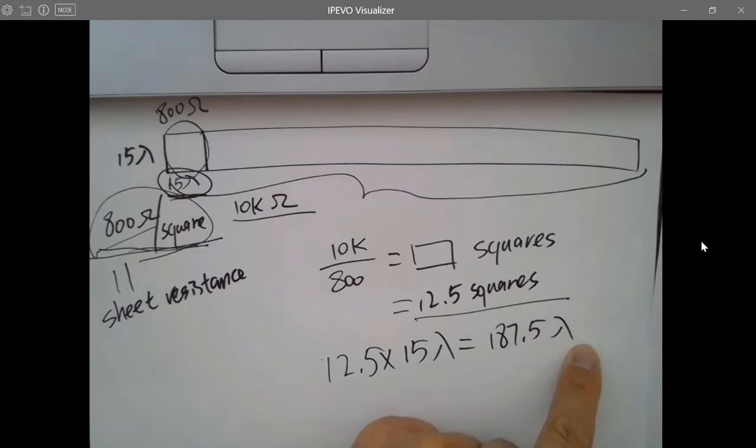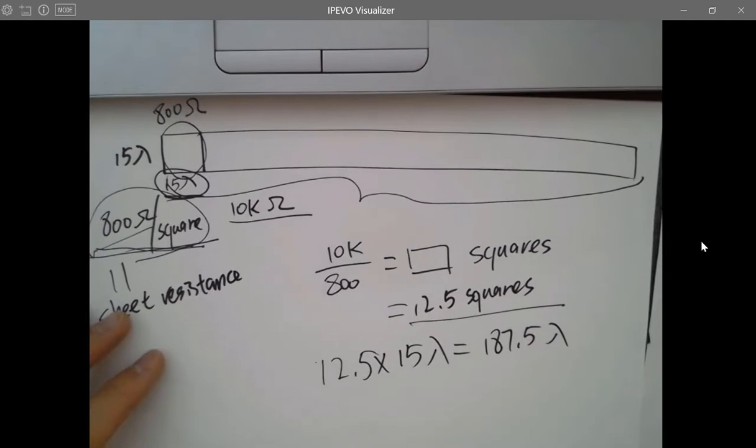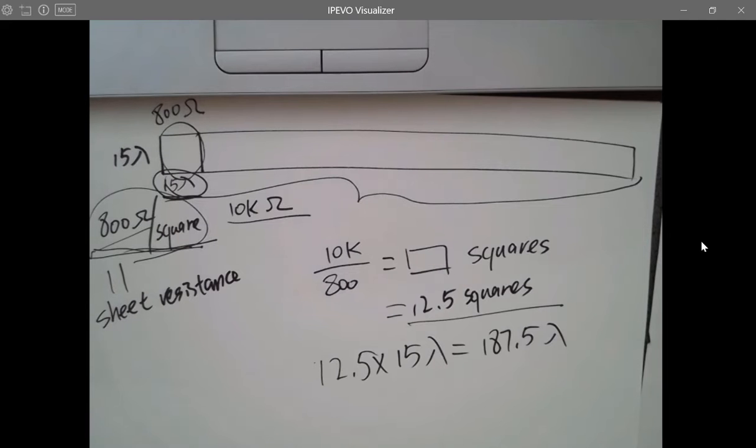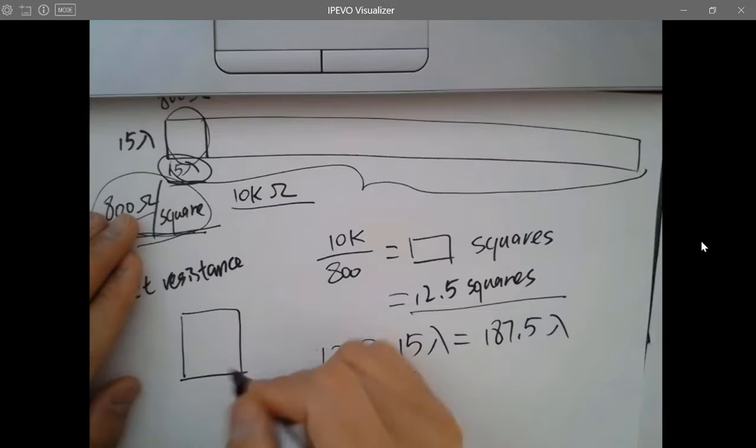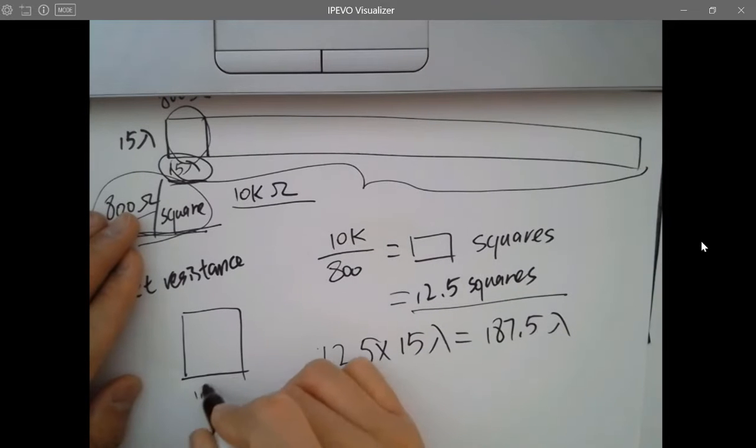I have to think about one thing, because resistors and capacitors normally take a lot of space on the chip. So before you lay it out, make sure it's not too long. You know, the die in the C5 technology, the little silicon die, is only 1.5 millimeter.